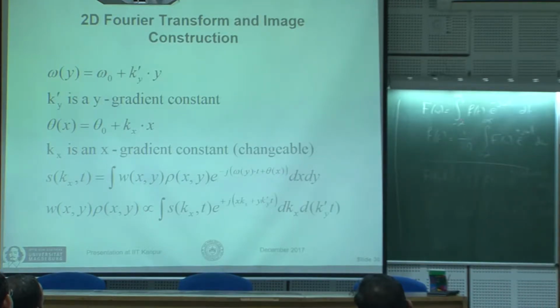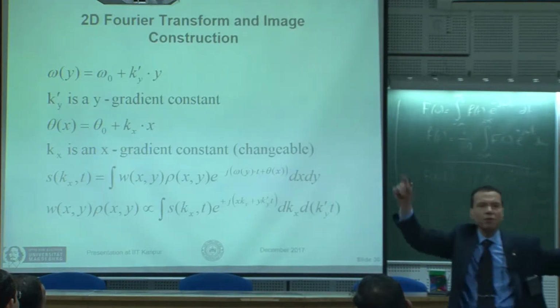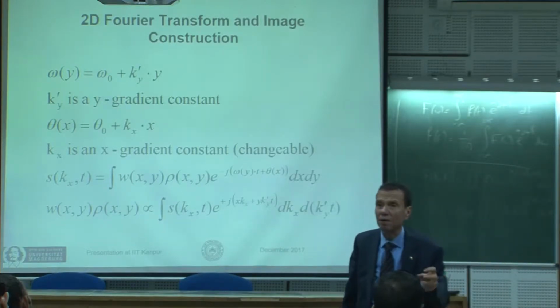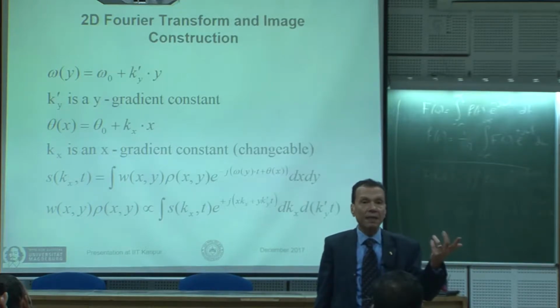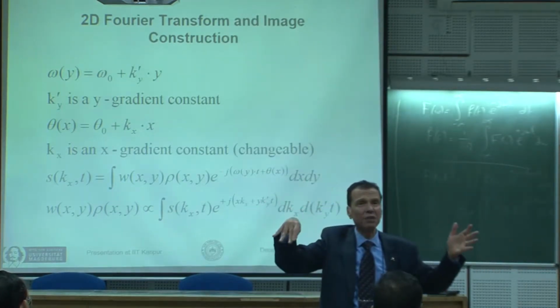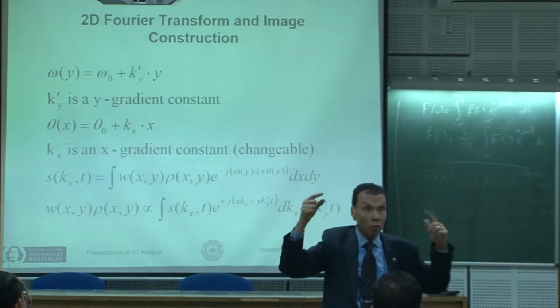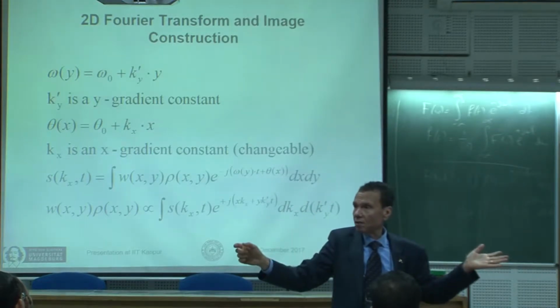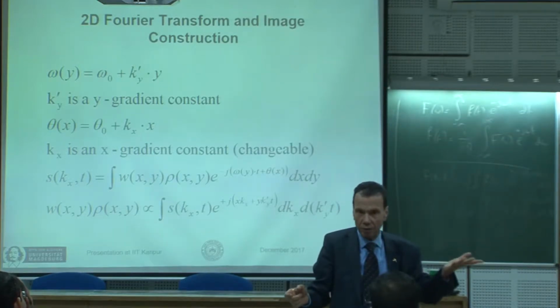Okay, now regarding sparse sampling, or what is called compressive sampling. Imagine that for a time signal you have a sine ωt or cosine ωt. If you look at the time domain, it is something which continues forever. And if you apply Nyquist blindly, I will sample, and I have no idea about the nature of the signal itself. But if you perform a Fourier transform, you will find out that this infinitely long signal is just a Dirac, or if it is of finite width, maybe a sinc function. And for a sinc function, you need the magnitude of the main lobe and the first zero, and that's all. So you need just two pieces of information for a sinc function.